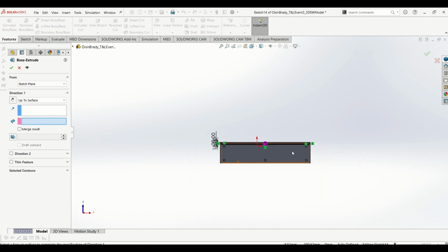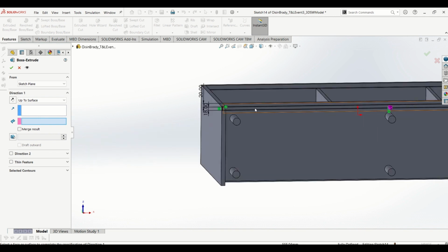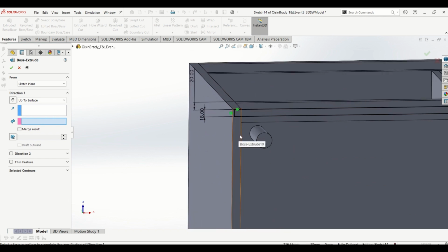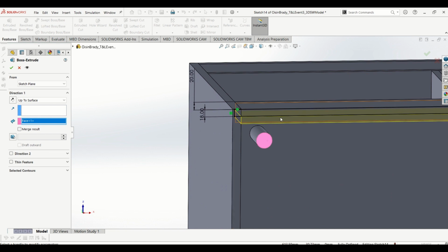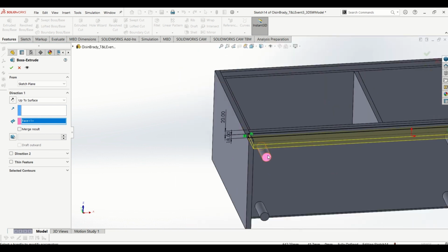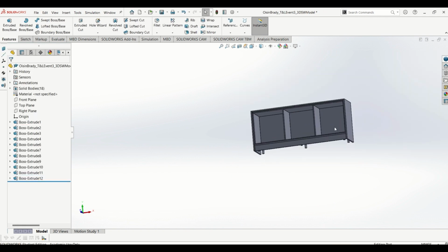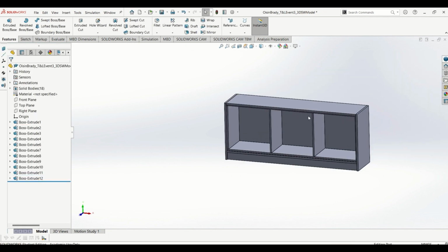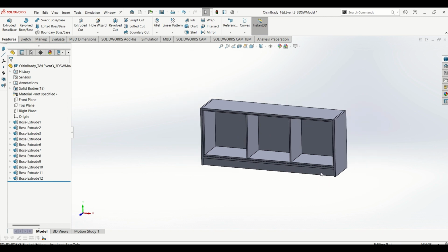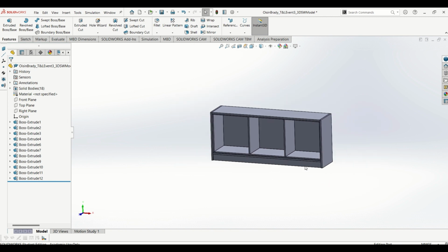So what this will allow us to do is go ahead and select the very bottom of our feet because we want our plinth to go down to the floor. And that will make sure that our plinth goes to exactly that depth and no further. I'll hit enter. You can see now we've fully wrapped our cabinet to hide the whole internal cabinet and the feet.